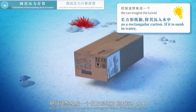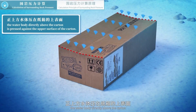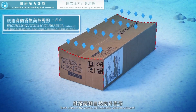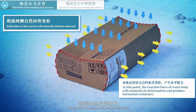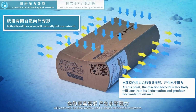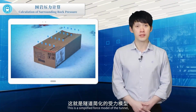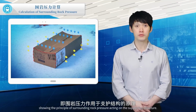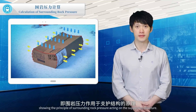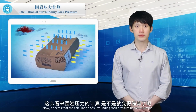If it is sunk in water, with the water body directly above the carton, both sides of the carton will naturally deform outward. At this point, the reaction force of the water body will constrain its deformation and produce horizontal resistance. This is a simplified force model of the tunnel, showing the principle of surrounding rock pressure acting on the supporting structure. Now, it seems that the calculation of surrounding rock pressure becomes simple.